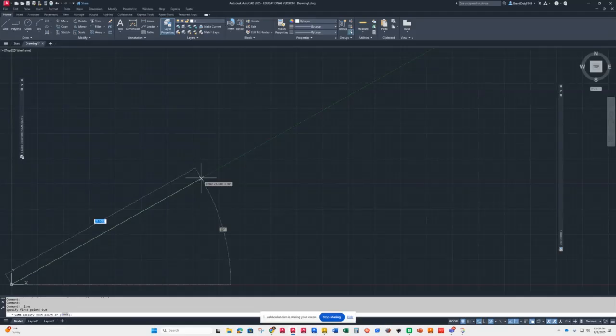I'm just going to pick a spot in space and draw. Now remember, if you set polar on, like I have mine on 15 degrees, so every 15 degrees, this is 30 degrees. Now, I don't have to put in a relative coordinate. I can teach you how to draw without using relative coordinates, but you have to understand what coordinates are, because there's times when a polar coordinate is the only way you're going to get what you want. And I'll explain.